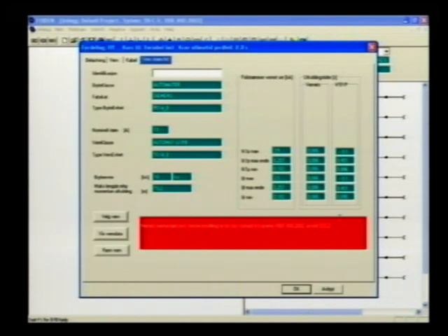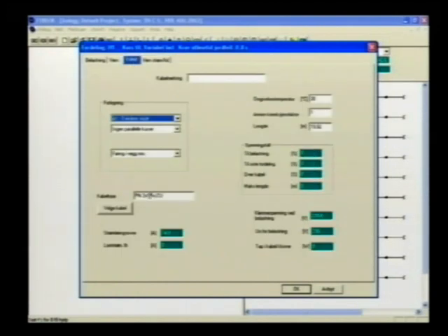And I click there on the device, and here is a red label down here saying, sorry for the Norwegian, that the rating current of the protection device is too high according to the regulation, referring to a specific clause in the regulation. I think that Trond Inge has said that he has to use 1.5 square millimeters cross-section of the conductor and have a 13 amps rated protection device, and that's not allowed in Norway when you have closed. So we have to do something.